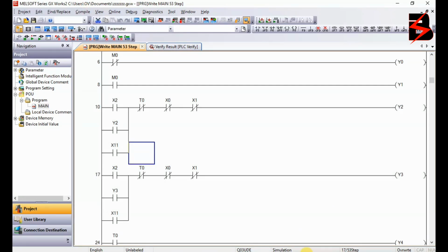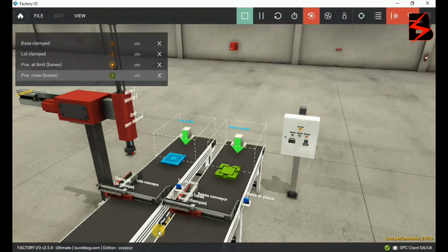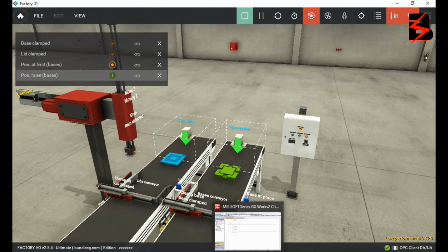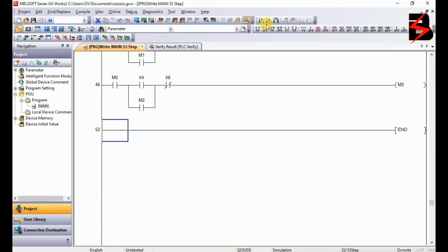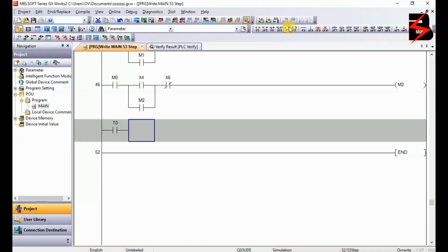We still continue. Now we are going to move to another output device, and that's Y6. What is Y6? Y6 is moving down the x-axis for the handle to go and grab the item. It is also going to be controlled after a given time interval, but also after a certain sensor reading, which is going to initiate the timer.